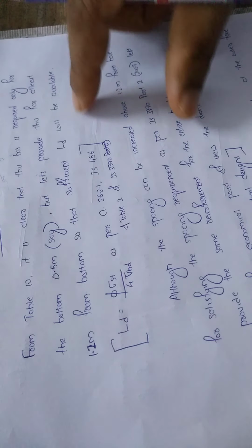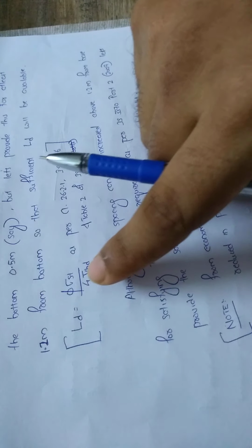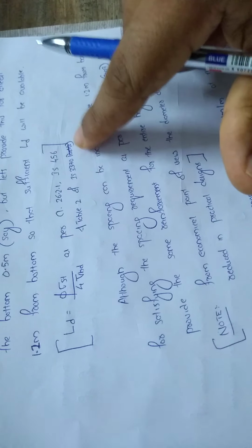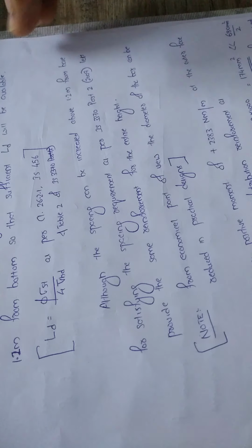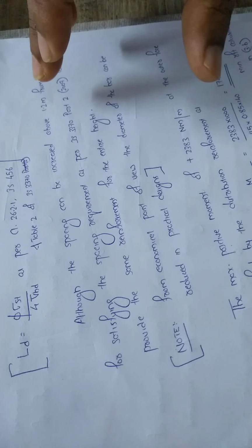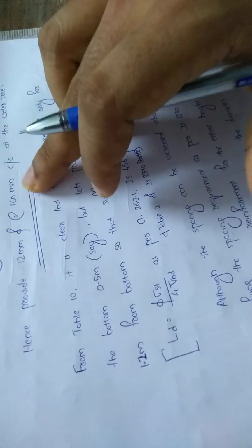Okay, so let us provide this for a minimum 1.2 meter height from the bottom, so as to be sufficient for development length also. Development length is 5 sigma st by 4 tau BD. The tau BD, the bond stress, you are getting from part 2 of 3370. But I am not going to change the spacing of the vertical reinforcement, because we have seen that the minimum spacing of the reinforcement is the thickness or 300 mm. Here it is only 170 mm. What we have provided is 12 mm at 160 mm.